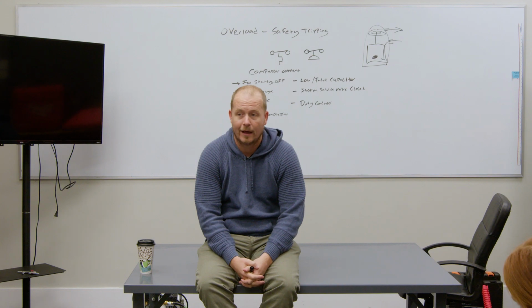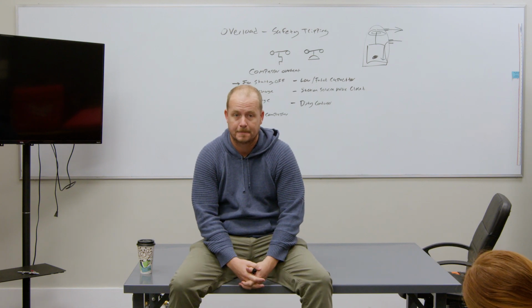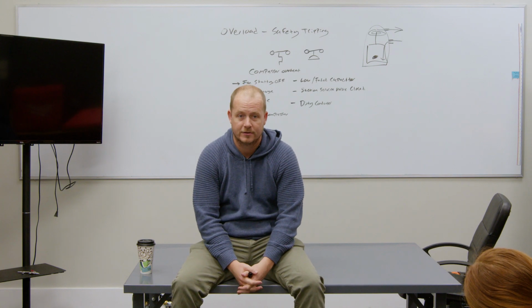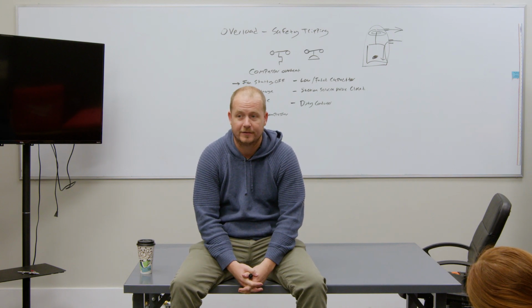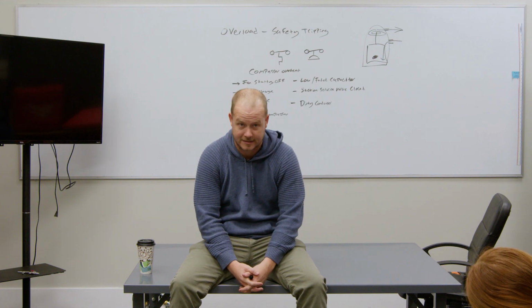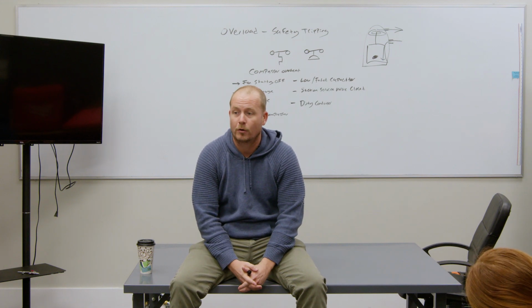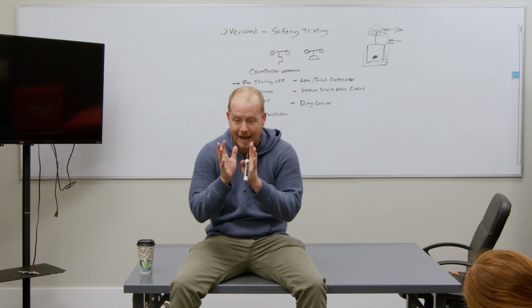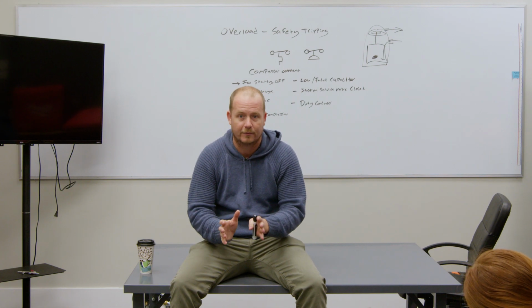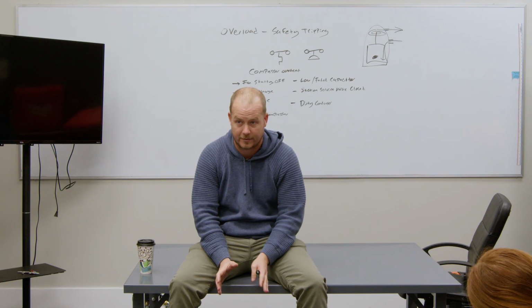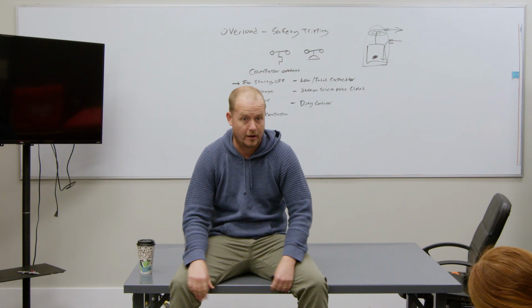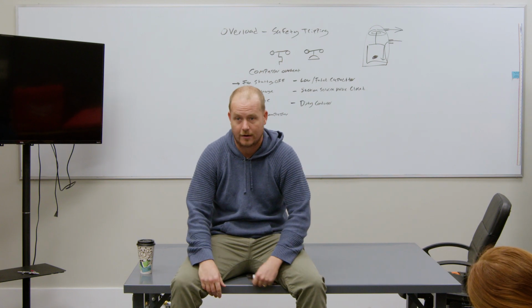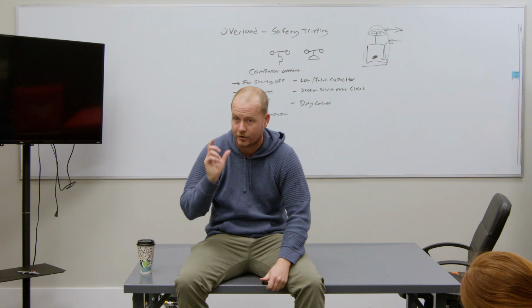That's fine. All I want is I don't want us condemning compressors when the compressor isn't bad and there's some secondary cause. Because even then, if you replace the compressor, you still haven't solved the secondary cause. So the primary thing to anchor on here is get the darn thing reset if you can reset it. Don't be impatient with it. Just because you ran a hose on it for 15 minutes and it's still not running, you say it's out on thermal overload and needs a new compressor. That's what I don't want you to do.